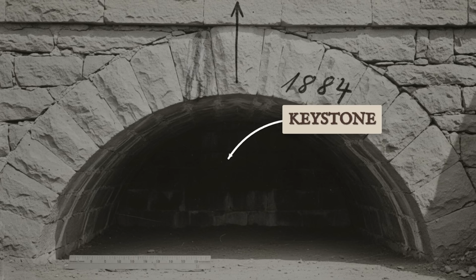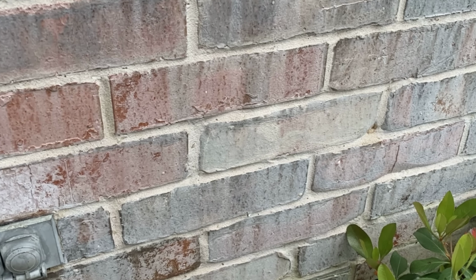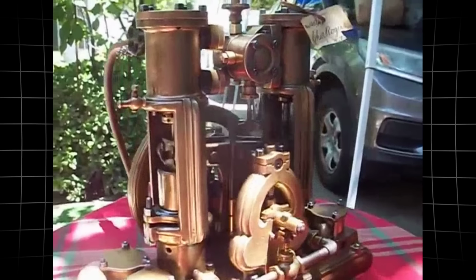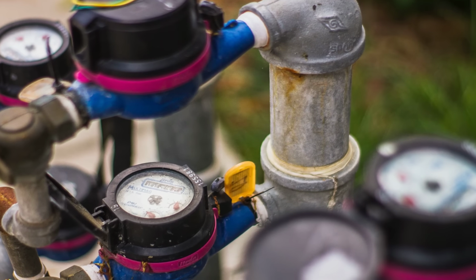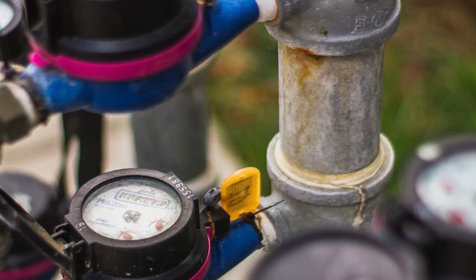The Canal Street photograph showed one detail I had not noticed initially. A water stain on the sub-arch surface ran vertically from the joint line. Water stains normally run downward. This one ran upward, suggesting water under pressure flowing through the stonework itself. Hydraulic systems can push water upward. Decorative foundations do not require pressurized water flow.